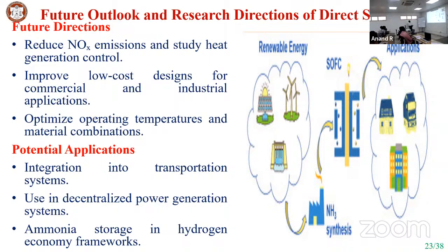Naturally, when using ammonia in an engine, you are already bringing in 79% nitrogen from the air. Along with that, the nitrogen dissociates further during burning, and more nitrogen compounds come out. It also leads to more NOx emission compared to burning diesel fuel in a diesel engine or petrol fuel in a petrol engine. So we need to take care of that. That is why, for ammonia utilization in engines, the problem of NOx emission, if it is controlled in the engine itself or in the exhaust itself, is going to be acceptable.